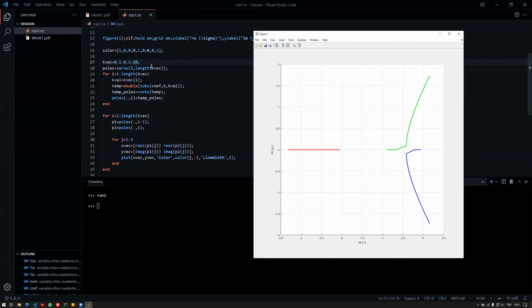Now, shouldn't we increase the interval? Shouldn't we decrease the interval in order to have a better and a more exact root locus plot? Of course we do, but don't forget that the root locus gain is starting from 0 and it tends to infinity. So we should also cover the bigger values, the huge values also. But we need also a certain precision, and we are lacking that.